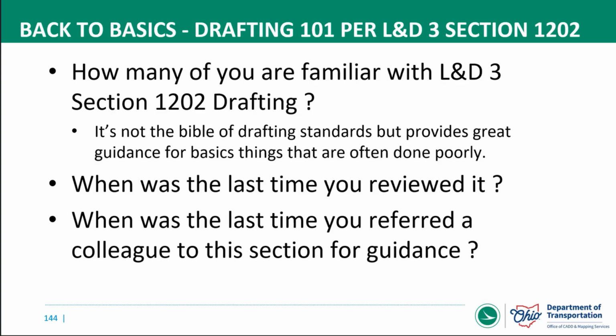1202.1, plan scales. Keep in mind, all of our drawings are produced for a full-size plan at 22 by 34, and almost all the time reduced to 11 by 17 print. So keep in mind that the person in the field is most likely going to have an 11 by 17 piece of paper with them. A mentor of mine once told me a long time ago, if you can't take that drawing, crinkle it up, spill a little bit of coffee and dirt on it, and make a photocopy of it, it's not good enough. So make sure that it's not overly cluttered and everything is legible.